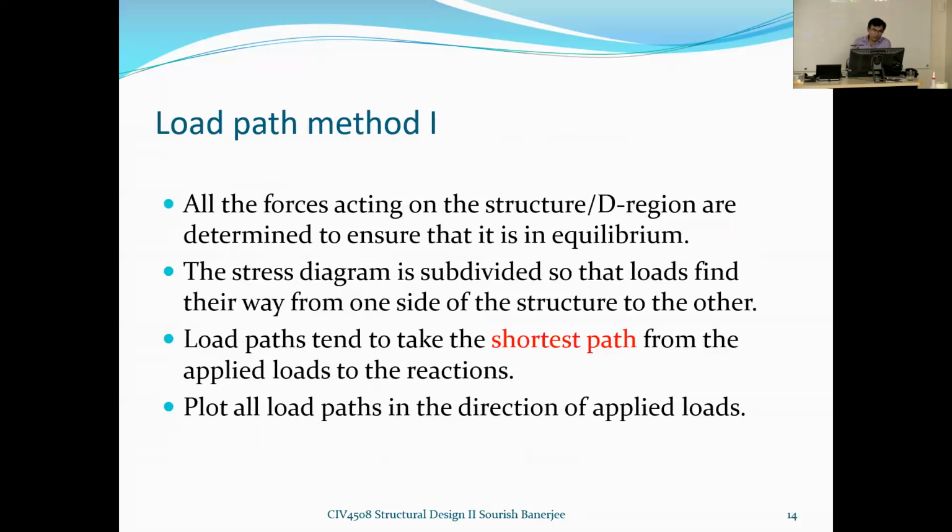Continue to the second one, which is the load path method. All the forces acting on the structure or D region are determined to ensure that it is in equilibrium. Suppose we are designing a structure like this, an arbitrary one, which is your D region, and it is subjected to different kinds of forces or reactions. You have to ensure that this D region is in equilibrium with respect to all these reactions and the forces it is subjected to.